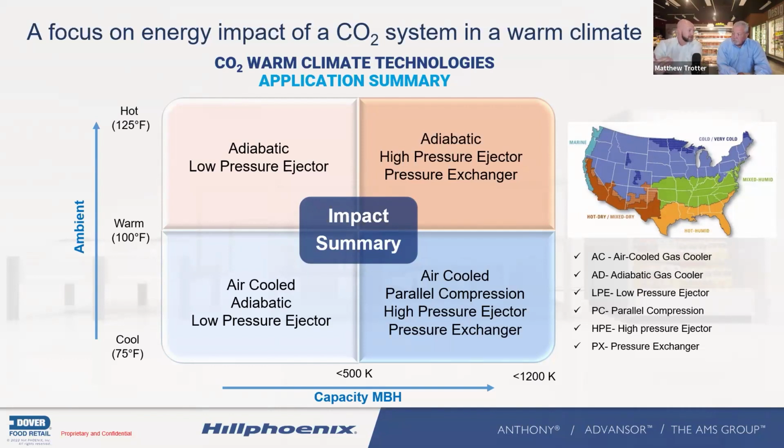But when we can't get that change of state, we don't have just one option. There's the adiabatic, where we drop 2 degrees above dew point, I think you said, which can be a 12 to 15 degree temperature drop of air going across the coil, giving us additional heat rejection. You also mentioned parallel compression.